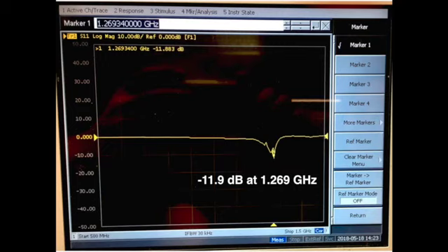This means that this is a resonance frequency of the cavity resonator, and as it is seen, there is no lower frequency in which this is lower than minus 10 dB. This shows that this is the dominant frequency for the cavity resonator, and so the goal is achieved.